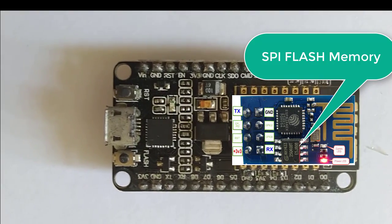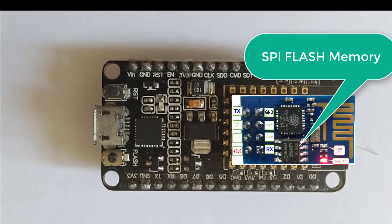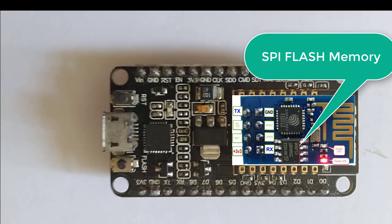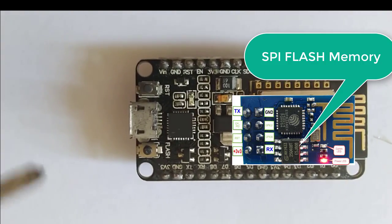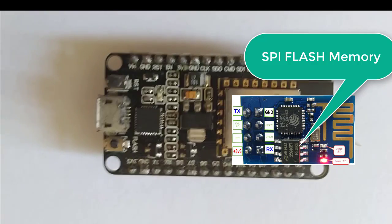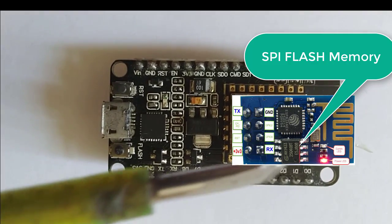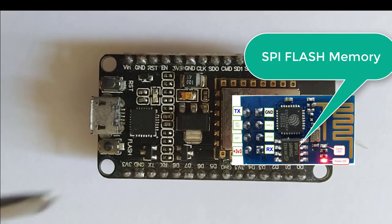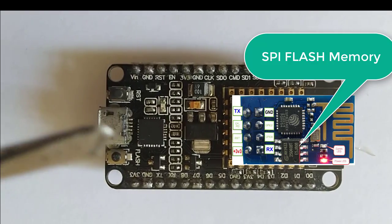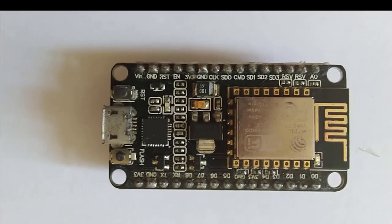Why this external SPI flash? Whenever the ESP8266 is working in station mode, station mode means it has to connect to another router which is enabled with Wi-Fi. In station mode, all RAM is full of its programmable accessible data, so that's why the user's programs must be stored in external SPI flash. This external SPI flash is up to 4 MB, or if you want more you can also extend up to 16 MB.